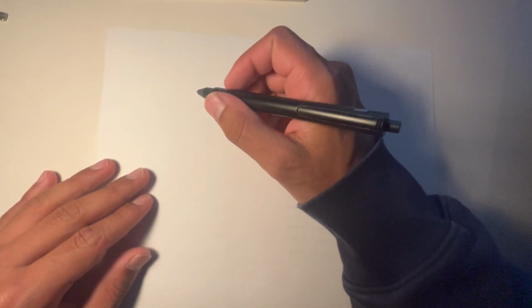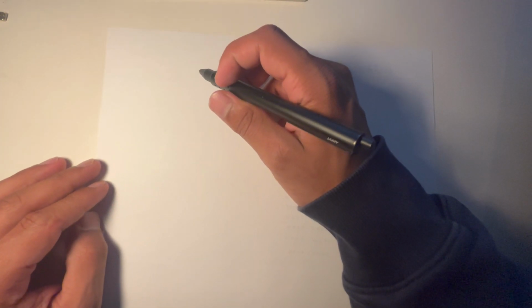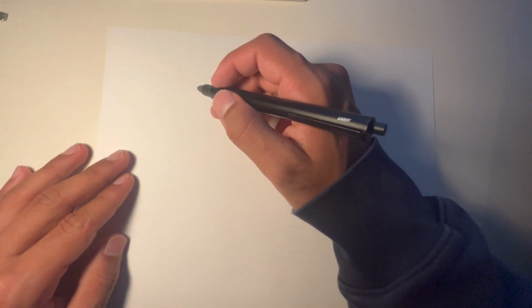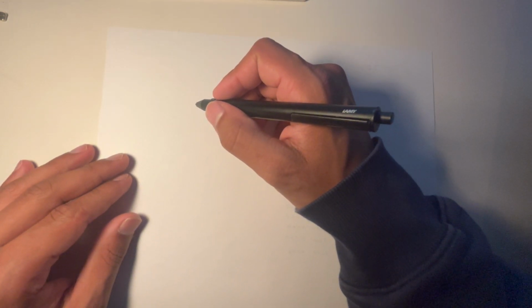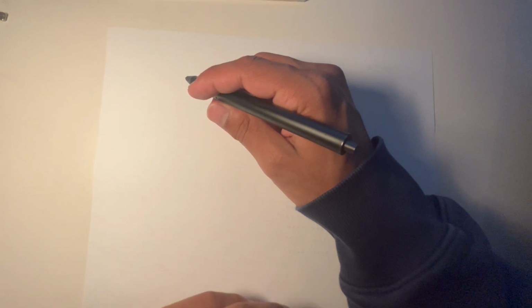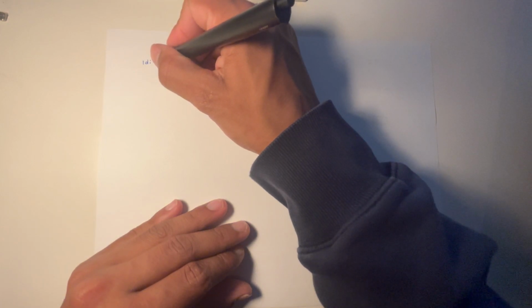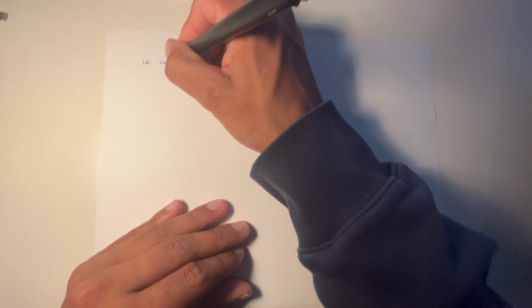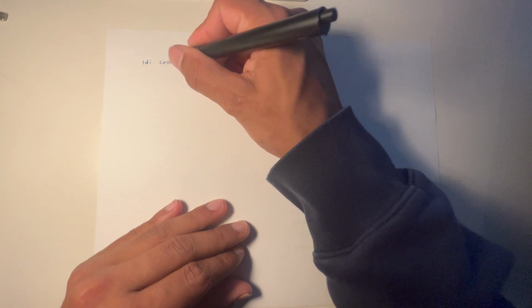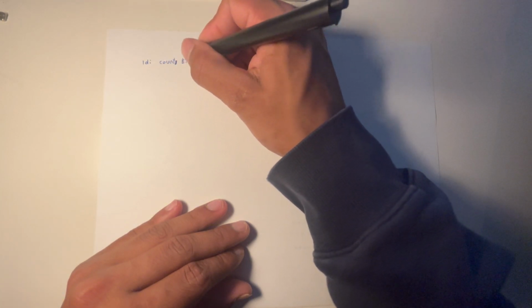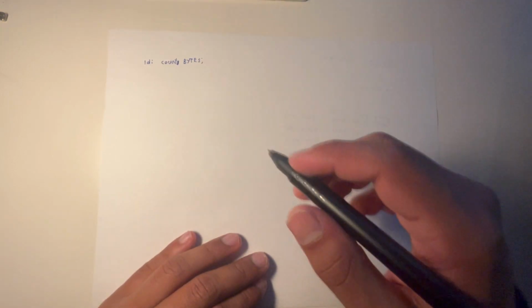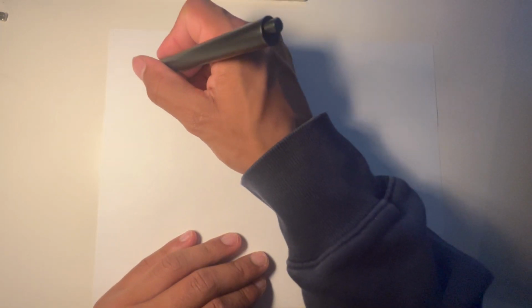So the first thing that happens is that a register called count is initialized with a value equal to 16 because we have a 16-bit value. So the first line is load immediate, and then we're putting the number of bytes, which is a predefined, into the register called count. So count, comma, bytes. Next, we just want to clear all our registers. So that was the setup.